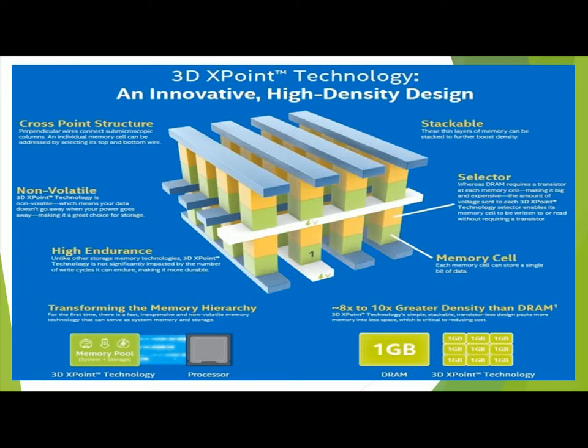It is denser than DRAM, and more robust and faster than NAND flash. It is basically a grid of parallel and perpendicular wires, and that's how a single cell is addressed. The cell is the address space and it stores 1 or 0. In old memory technology or NAND flash, the transistor detects the charge inside the capacitor to give 1 or 0. There are no capacitors and transistors here. If you have two wires connecting each other, that is a unique cell.